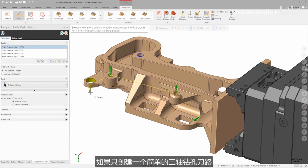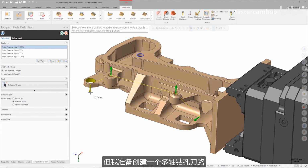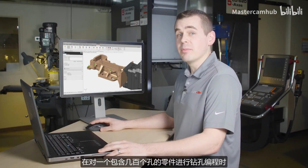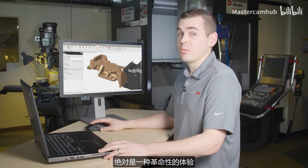If I was creating a simple 3-axis drilling operation, these arrows would have no effect on the toolpath, since the direction the holes are drilled from is controlled by the tool plane that is set in the toolpath parameters. However, I'm going to create a multi-axis drilling operation, so I need to make sure these arrows are pointing in the correct directions. I can change the direction of any of these arrows by simply clicking on them. Having all this information readily available, as well as being able to control my hole axis direction so easily, is a game changer when I'm programming a part with hundreds of holes in it.